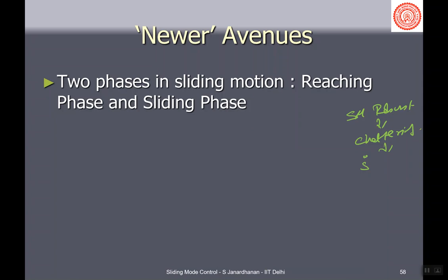Right. So yeah, the chattering was there. So what we needed was S dot not to be discontinuous. We needed S dot not to be discontinuous for chattering not to occur. But we didn't have a clear-cut solution for this.